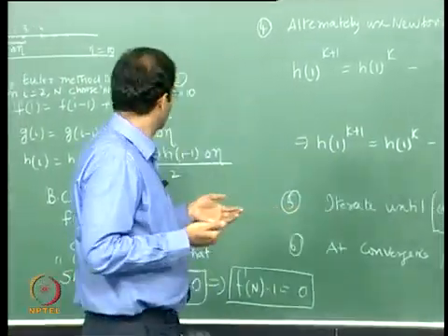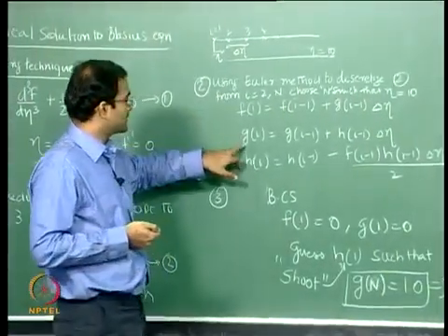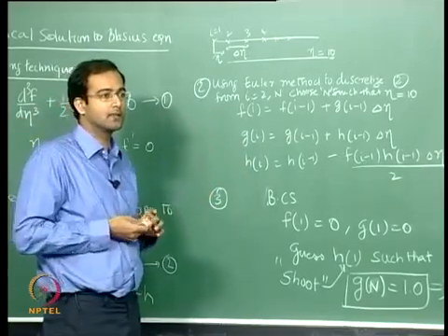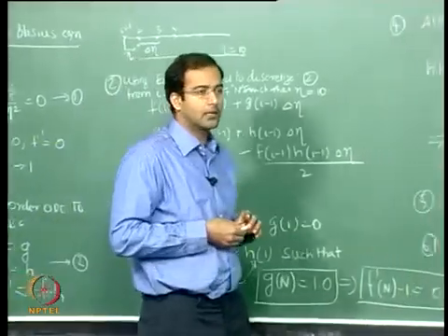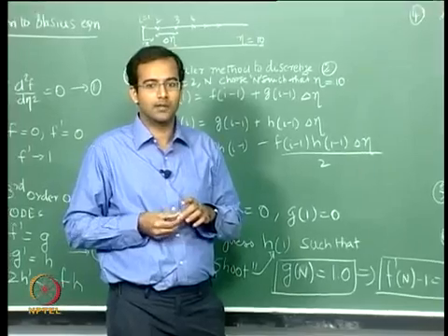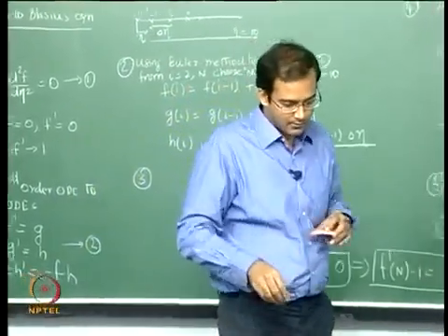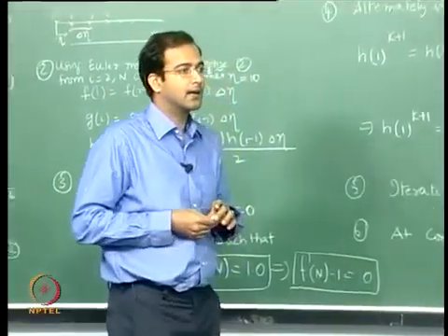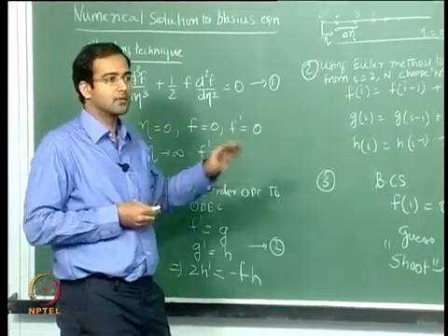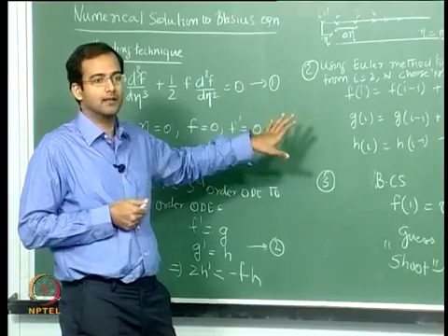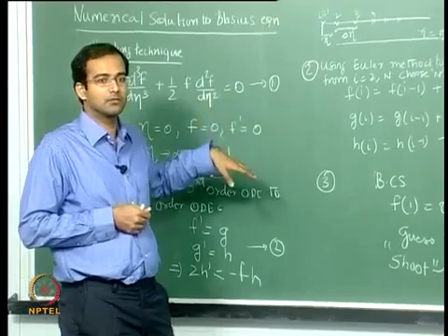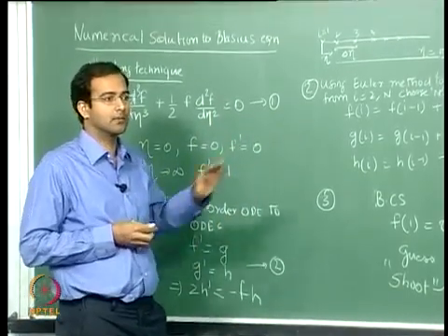Numerically you have f. So this is for f, this is for f prime, this is for f double prime. So you have all the solutions at all the points which you can plot, and you will be surprised to find you will be exactly matching the Blasius solution, whatever he did analytically. So this is a very good numerical technique, and we will have a few more ODEs in this course where you will be using the same method. It's identical, it doesn't matter how many orders you are looking at, you have to reduce that to n first order ODEs and you will be using the same technique.